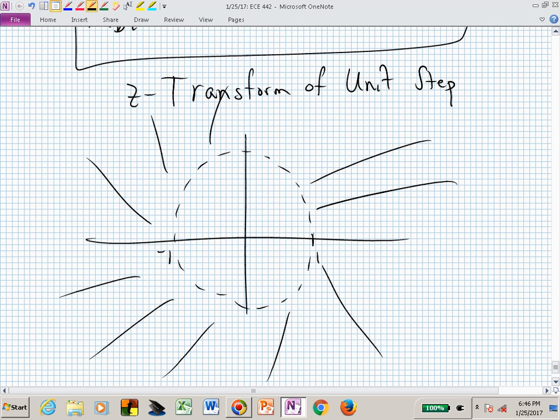But what I've shaded is the region of convergence, which is where that particular waveform was nice or well behaved. It was for values of z outside of 1 or bigger than 1. So the region of convergence is outside of 1. Here's j and minus j, and our pole was at 1, and we had a 0 there.